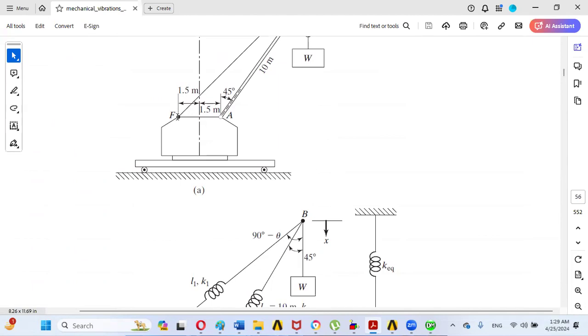So to create pin connections at point F and at point A, we will be using one displacement support with all X, Y, and Z coordinates to be 0, and one fixed rotation constraint, with rotation in XY plane to be 0, and rotation about Z axis must be free.